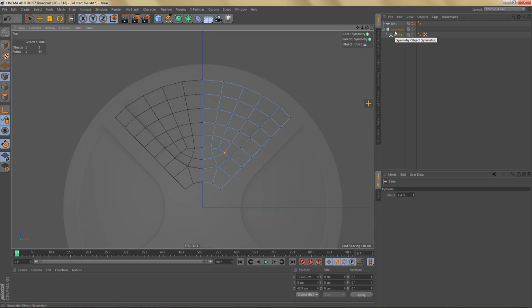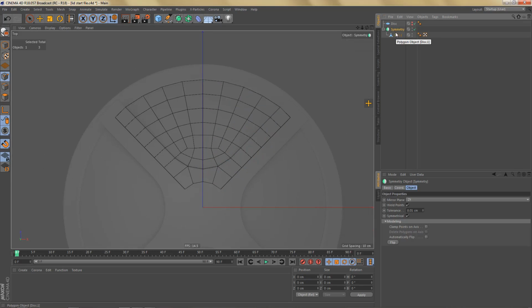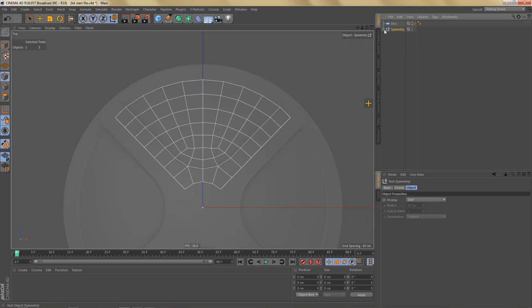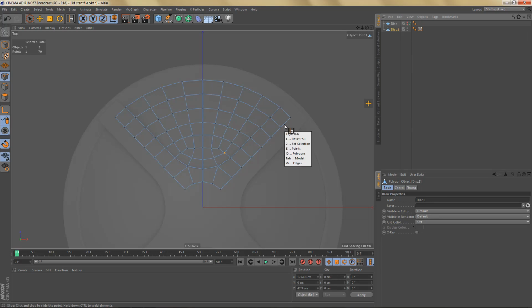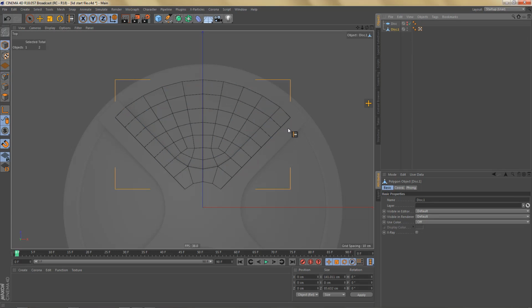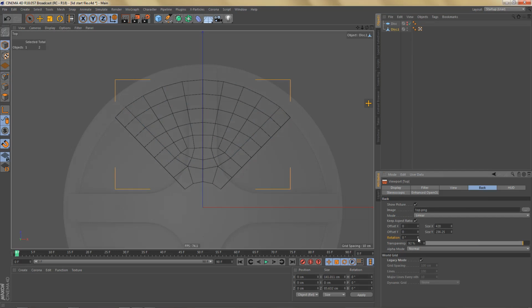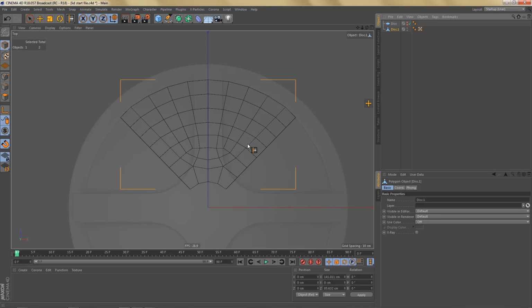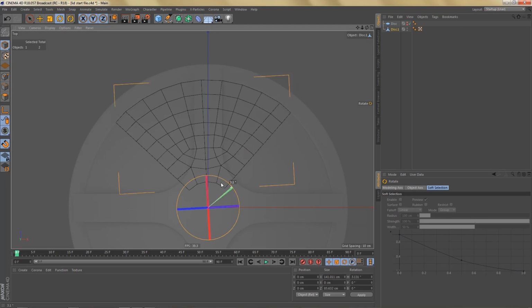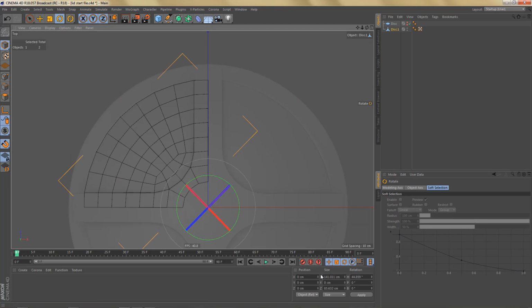And let's see, now we can make this symmetry object editable. And I'm going to rotate this around again. First of all, let's change the rotation of the reference image back to 0. And let's rotate our object here 45 degrees. And let's reset the axis.